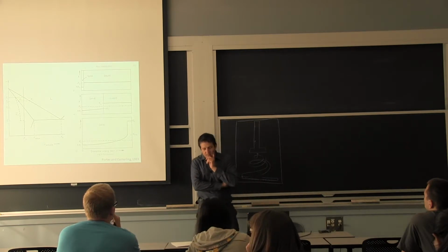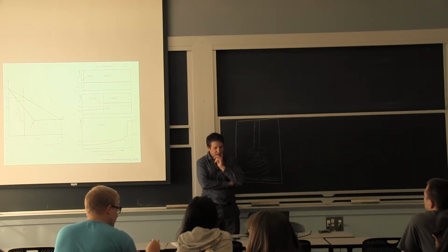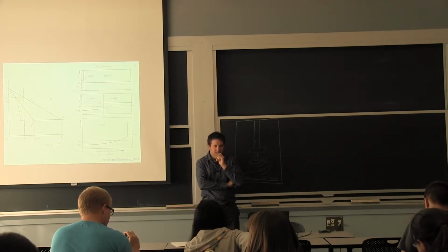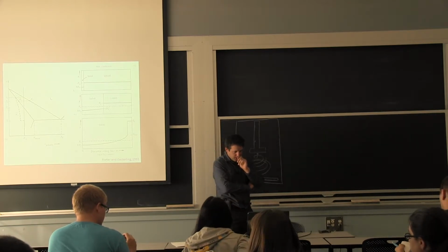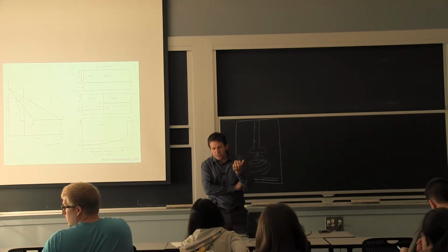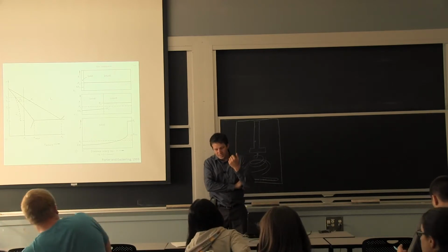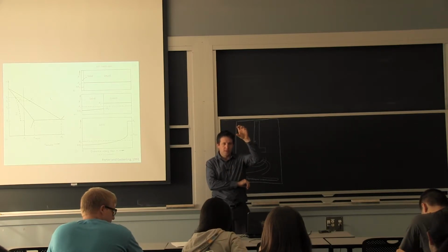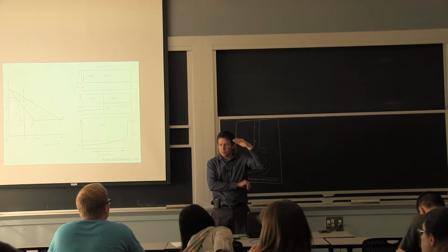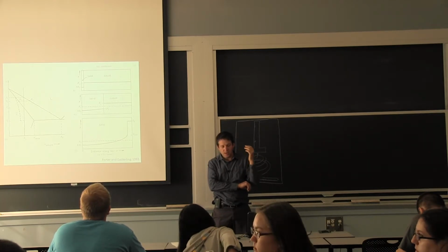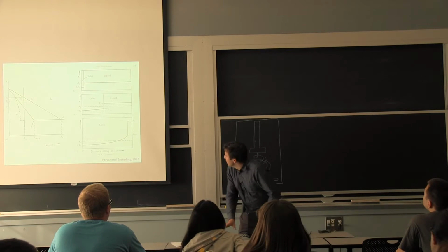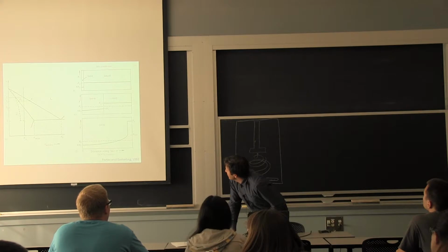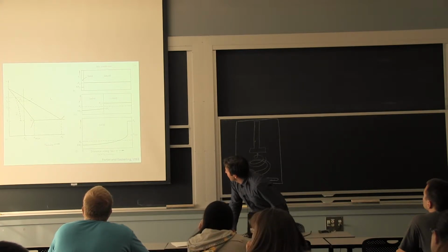We talked last time about segregation, and I think I mentioned to you that it was related to the phase diagram, so we're just going to go into more detail with that now. Most of the time we don't deal with pure metals, and we sometimes deal with pure eutectics, so something that will go from the liquid to the solid at a very specific temperature. But most of the time, we have some alloying element that has a reduced solubility in the solid. So the solid is this line here. This is just a simple binary phase diagram.